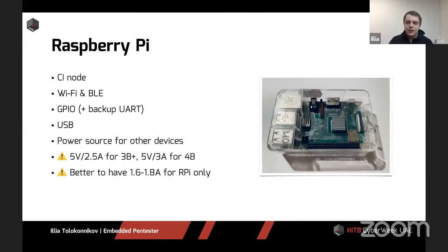And because we're running them, as I'll show later, from USB power bricks, we don't reach the whole 2.5 amps. So after some napkin calculations of all the devices we connect to it, we arrived at this magical number of 1.5 amps for the Raspberry only. Because if you give lower current than that, it can brown out, just hard shutdown when it starts to be loaded.